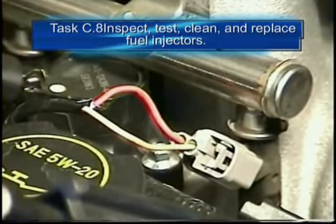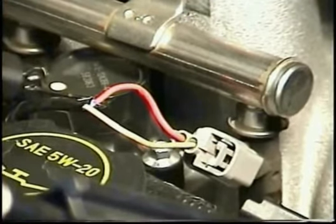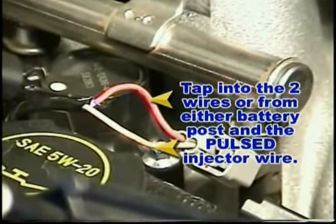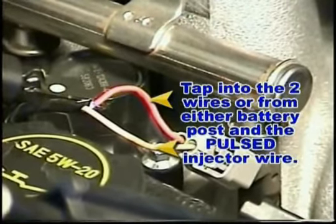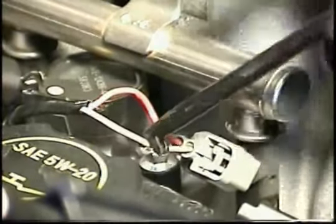Prepared to do a voltage waveform analysis of the injector signal. This is done by tapping into both of the injector wires using wire crimpers or any means necessary. You are measuring a different waveform, which is called a voltage waveform, and by analyzing it, a different set of characteristics can be derived. This is an intrusive test and involves piercing the wires to get to the copper element. In other words, a physical contact is needed.